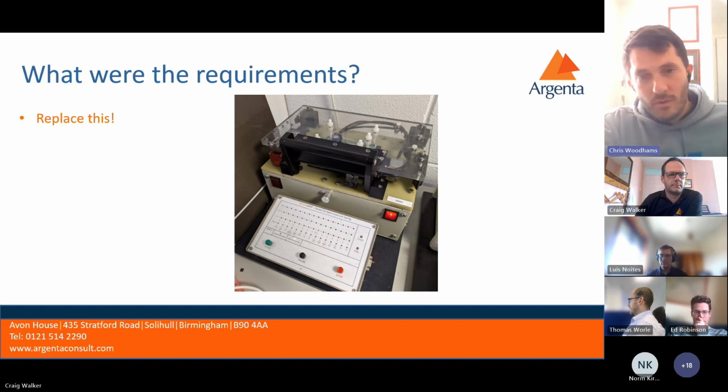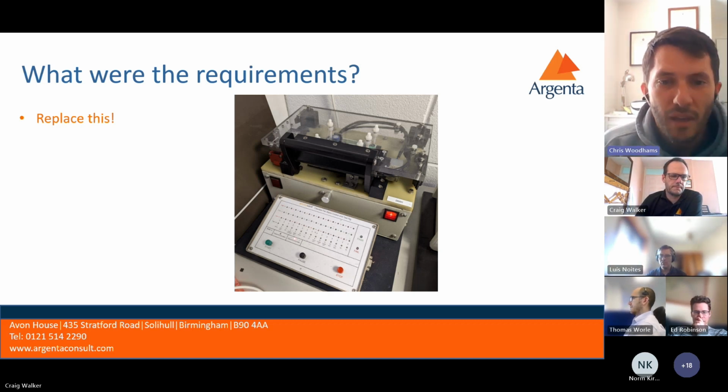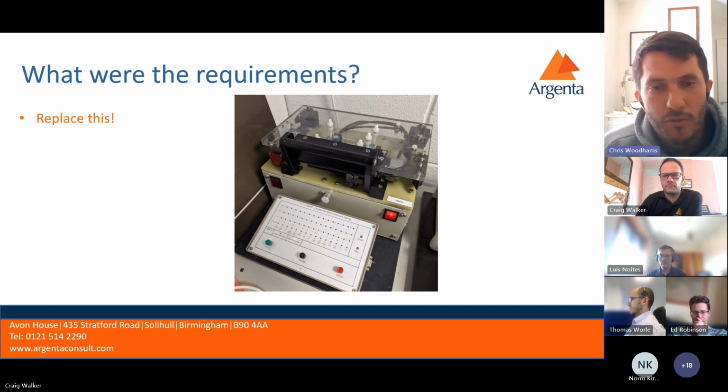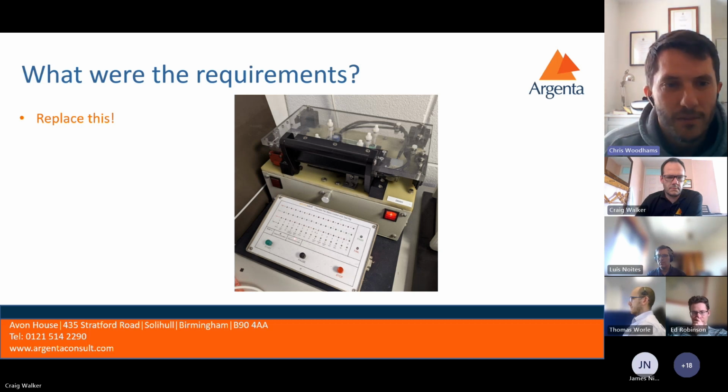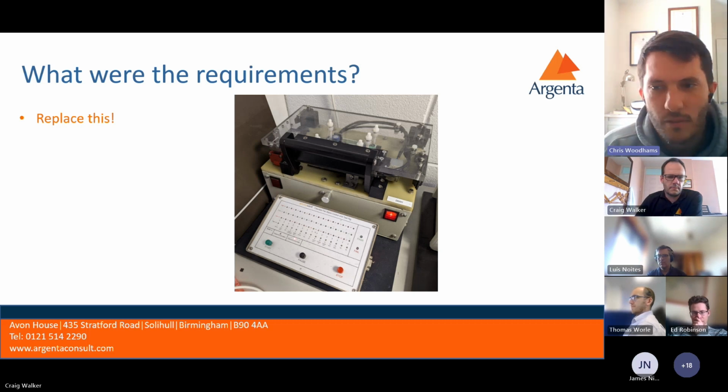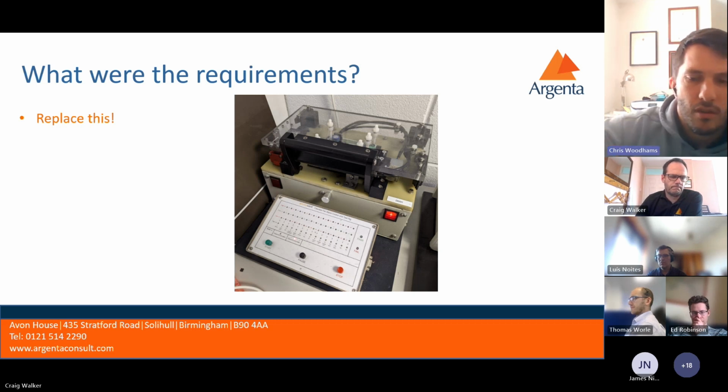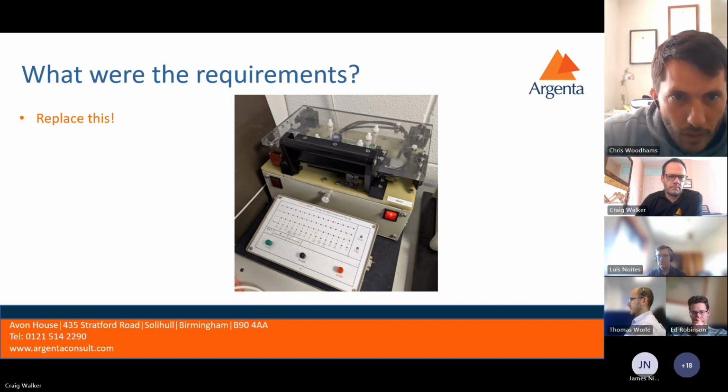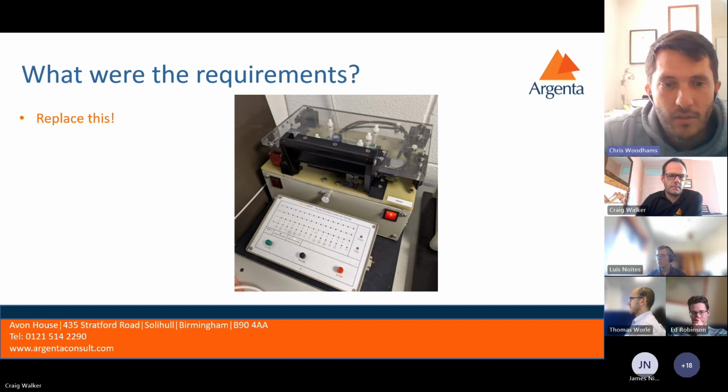Obviously, we had a test sequence that was associated with the PCB, and a load of other detail about what kind of interaction was required with it from a programming the PCB perspective, but also test points and setting things via UART and things like that. So quite a lot of interaction with the PCB that needed to be managed through the jig.